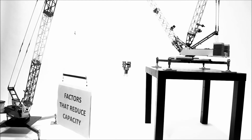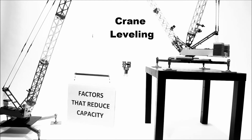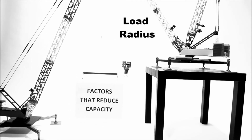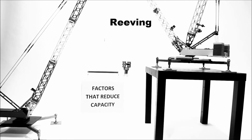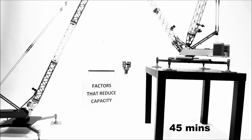Factors that reduce the capacity, Learning Session Number 6. Equipment condition, crane leveling, ground and soil conditions, side loading, increased load radius, impact loading, duty cycle operations, eccentric reeving, and windy conditions. Estimated time for completion, 45 minutes.